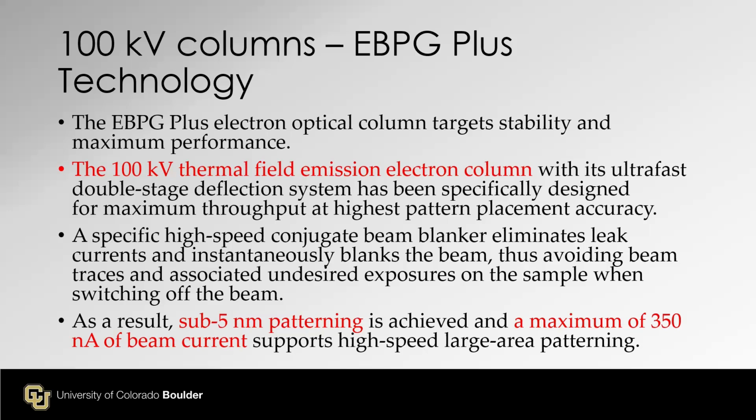When we use tungsten filament-based SEM for EBL, I use 5 to 10 picoamps for high resolution writing. So if you want to draw a 50 nanometer line using the tungsten filament SEM, we have to use 10 picoamp or lower for that system.